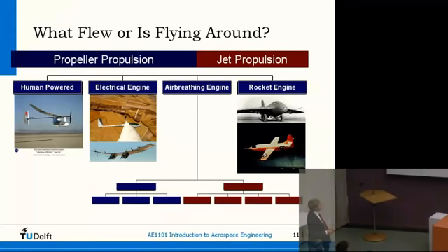Electrical engines, of course, they are around. There are already small aircraft which already have electrical propulsion. The question is, can it replace also the high-speed, long-range propulsion? Here we see, for instance, the one that's also solar-powered. In general, the amount of solar energy that the wing area catches is not enough to generate thrust for the airplane, even if you would have 100% effective solar panels. But maybe now I'm making the same mistake as the gas turbine committee by saying that that's not possible. Because the Solar Impulse, of course, is already doing something similar, but it's also halfway a glider.